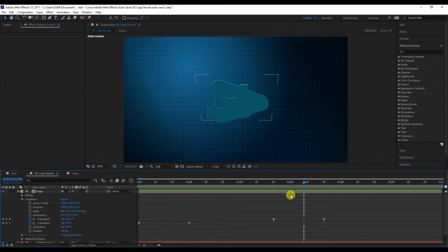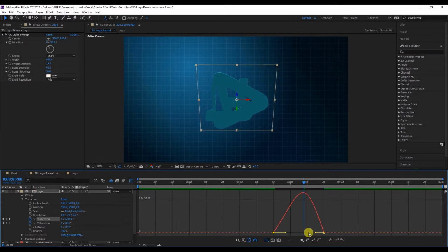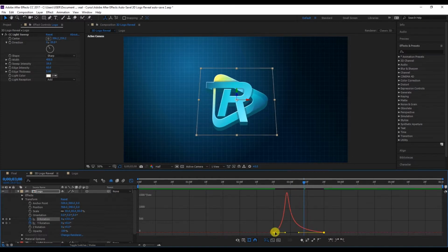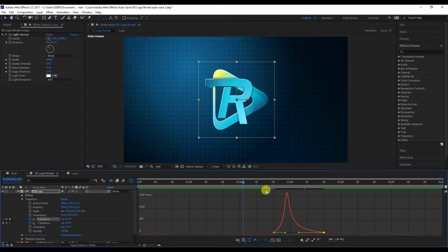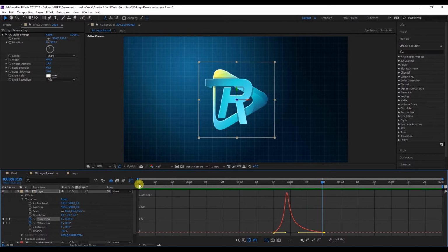We're going to modify again in the graph editor. Let's click. We'll go to X rotation, but in this case, we'll go to the edit speed option. Here, what we're going to do is click on the first one. We'll move it more or less to this part. And this second point, the anchor, we can put it here. So now we're going to see how it gets faster and finishes slower. Let's hit play, and there we have it. That's the effect that we've created.